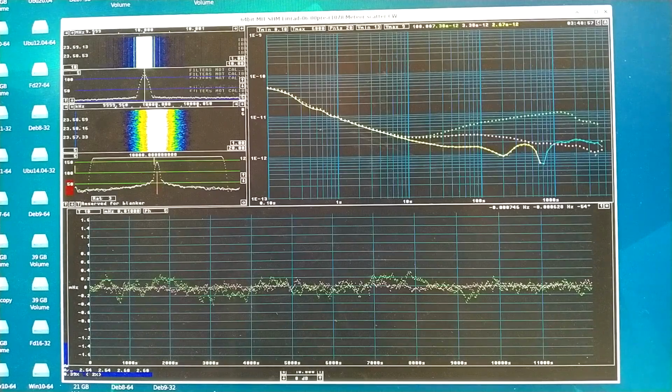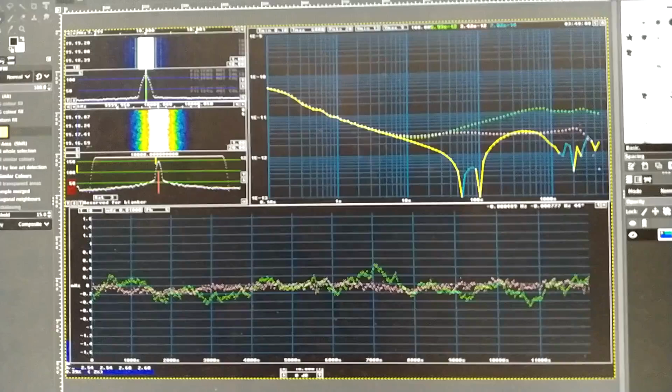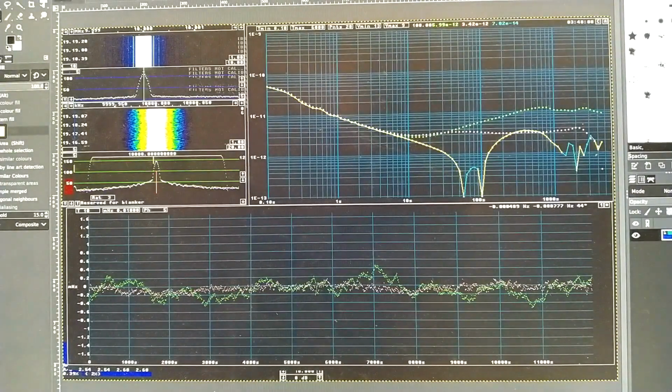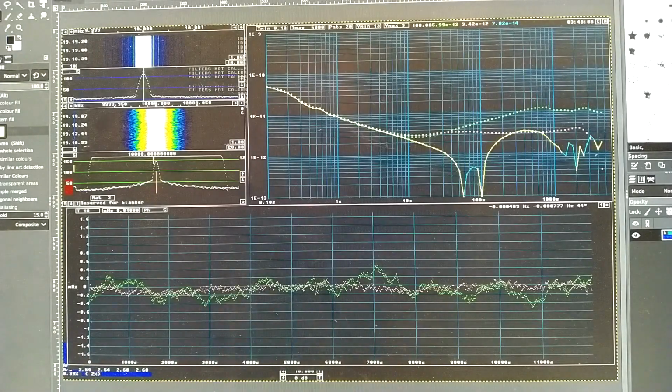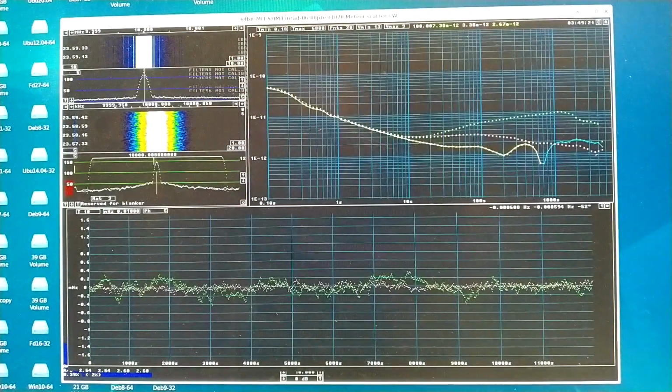Here the PLL resistors are set to 10 kilo ohm for both channels. And I can compare with what I had with 44 kilo ohms, which is this. And we can clearly see that the noisy channel 1 is a little bit better, maybe a factor of 2.